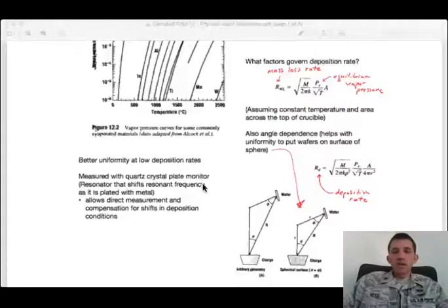Well, I don't have my metal atoms coming straight in parallel to this well, and so they're going to come in at some angle, which means that part of the well is going to be shaded from direct sight to that metal charge, right? And so atoms coming in a straight line, right? There is no straight line that leads them to be deposited on this side. And so you can get very poor step coverage, right, on this side of the step, reasonable over here.